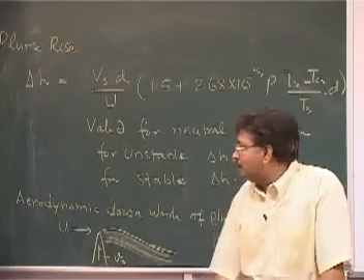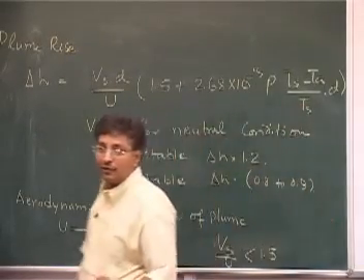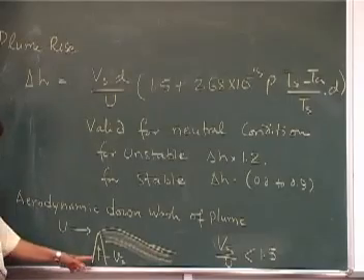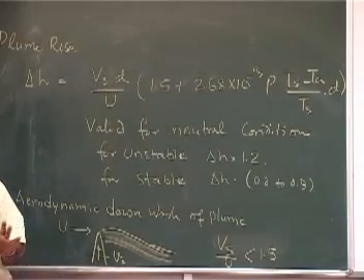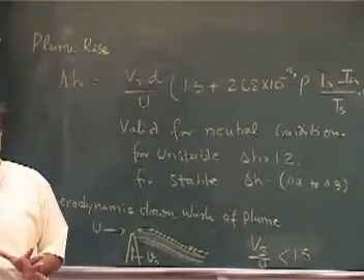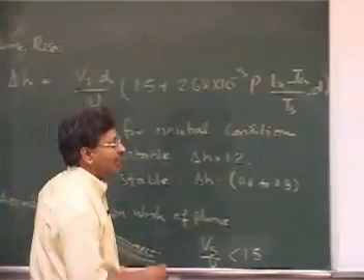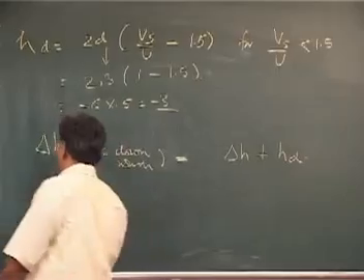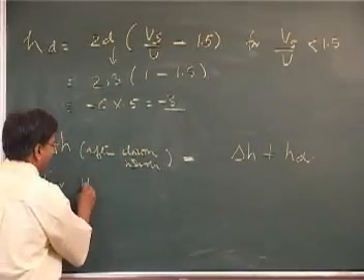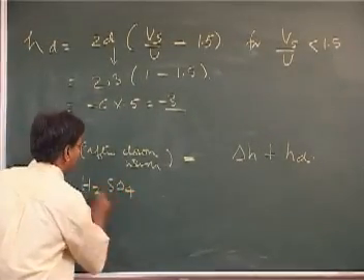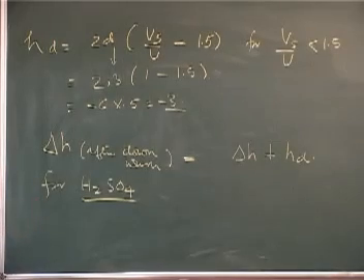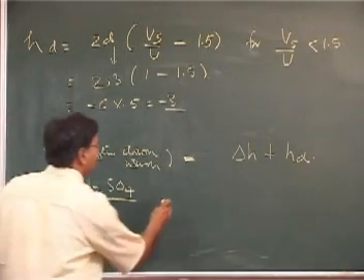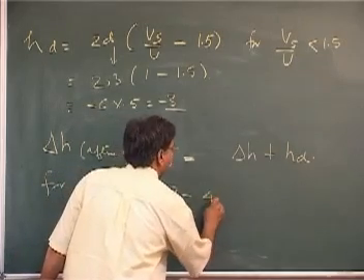Typically the way chemical engineers design a sulfuric acid plant, they design an exit velocity of, let's say, between 3 to 4 meters per second. For the sulfuric acid plant, what we measured was an exit velocity anywhere from 3 to 4 meters per second.